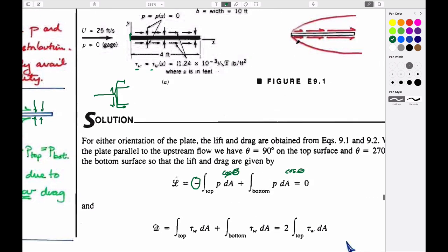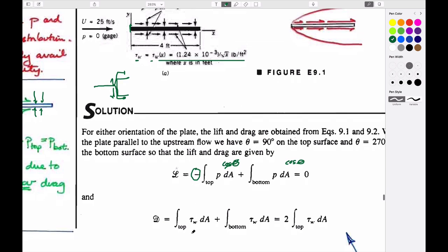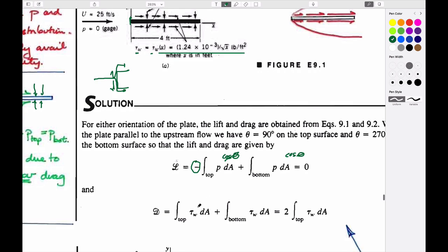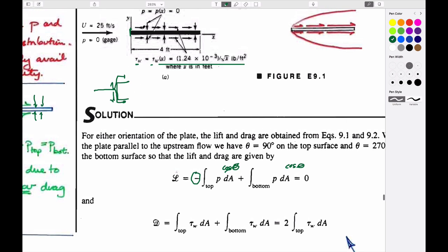If you look at the magnitudes of the shear stresses which are applied, given by this expression here, then the drag that you'd get would also be modulated by the appropriate cosines, I think in this particular case, to give you the magnitudes of these, which are additive. And you could just by inspection see that the shear stresses applied on this boundary would be the mirror image of each other on the top and bottom, and would be additive in terms of the integration.